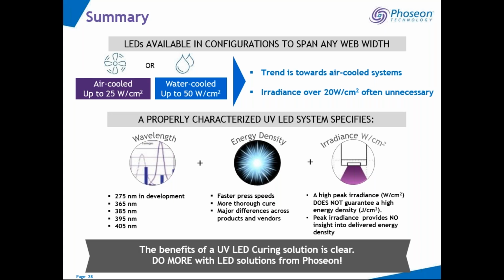We have seen that LED is able to penetrate that ink better than a mercury system because it has that deep UVA, UVB region. And so it's able to penetrate that ink, and it actually cures from the bottom up. So you're going to get great adhesion, you're going to get great through cure, and as long as the ink is formulated correctly, you get proper surface cure as well.